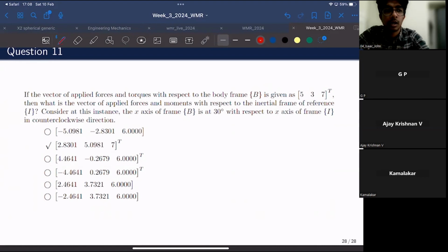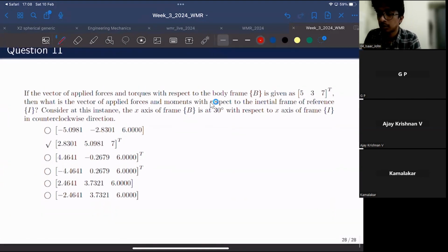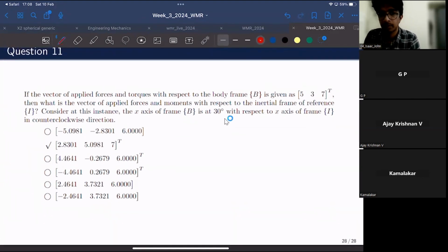When there are green wheels, we are putting the degree of mobility as one. But when it is two red wheels, we are putting the mobility as two. Is it that each individual wheel can be switched on and off by the user? That's the reason why we have two degrees of mobility. Yes. If there are two red wheels, then each of these two red wheels is driven by an individual motor. Individually they can be controlled. That's the reason why mobility is two.